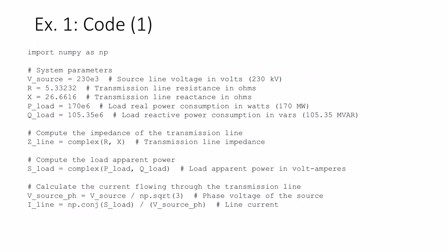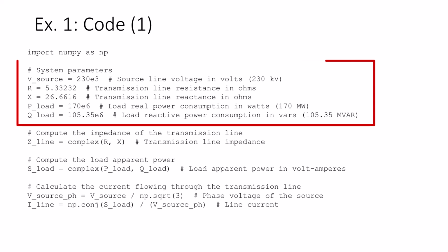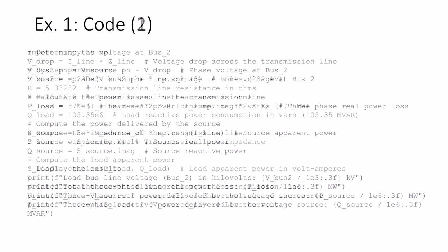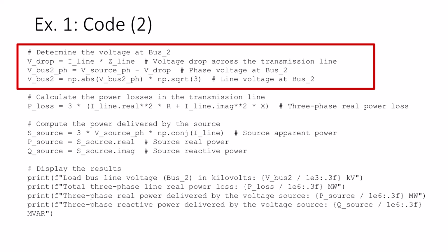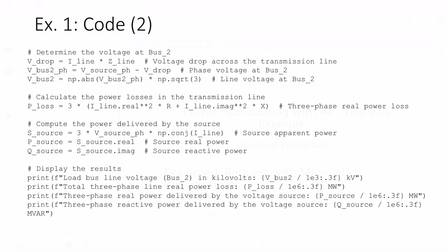When we examine the code, at first glance, it looks as if we might have a working power flow. The program properly defines the circuit parameters as included in the chat input. However, when we look at the code algorithm, we see that the voltage is not iteratively updated as discussed earlier. The program simply computes a voltage based on a first iteration.